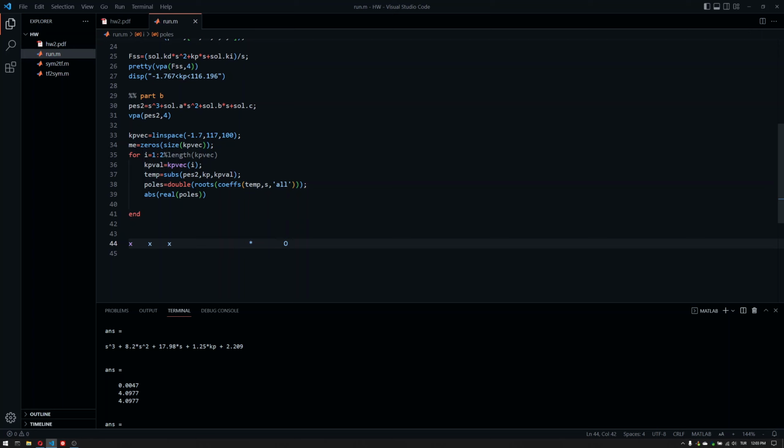Now, I'm interested in the closest one, the closest to the origin, because it doesn't make sense if I have these two poles, because this one is the closest one and it will have effect on the dominant pole pair. So I should look for the minimum distance, or the minimum one, of the residue poles, because that would be the closest one.